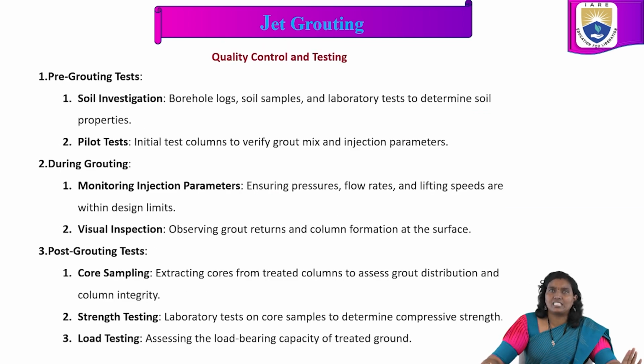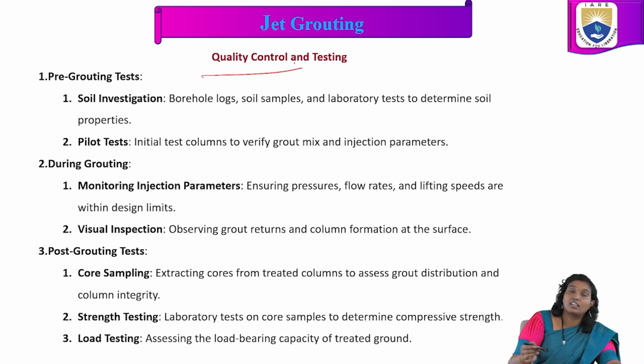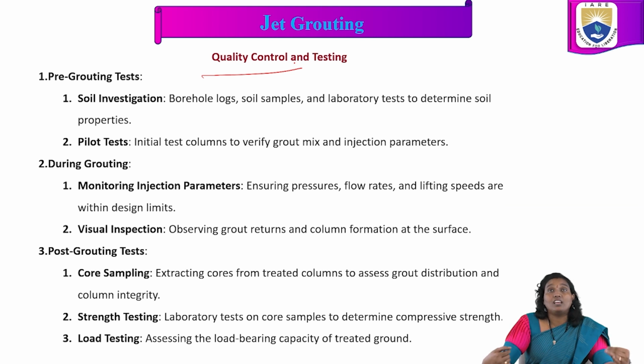Quality control and testing. Pre-grouting tests, tests during grouting, and post-grouting tests are available for quality control. In pre-grouting tests: soil investigation, borehole logs, soil samples and laboratory tests to determine the soil properties; and a pilot test, an initial test on columns to verify grout mix and injection parameters.